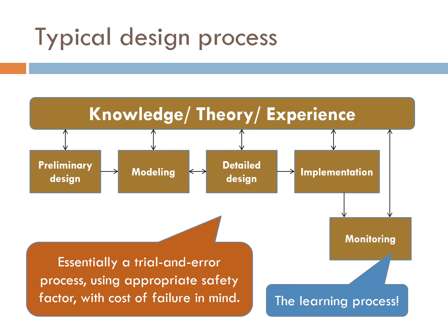By installing suitable gauges or making frequent visits to the site, and also carrying out suitable on-site measurements at regular intervals, engineers can find out whether the structure has the positive impact as desired or whether it has actually induced some unexpected negative impact to the local environment, including the littoral processes.